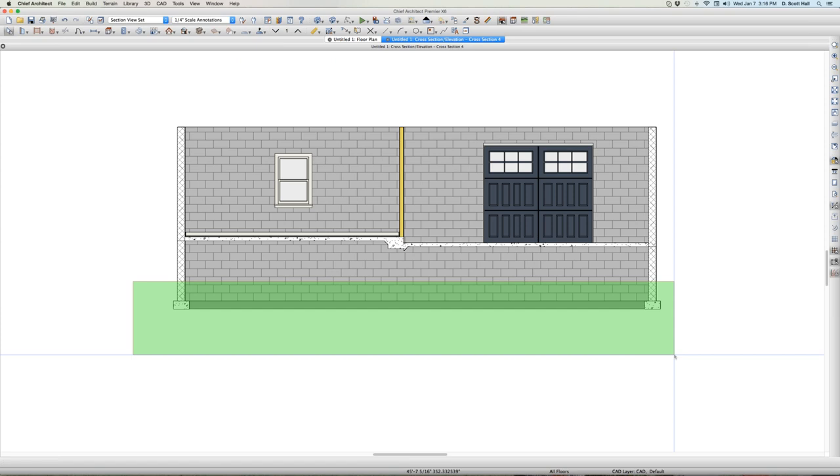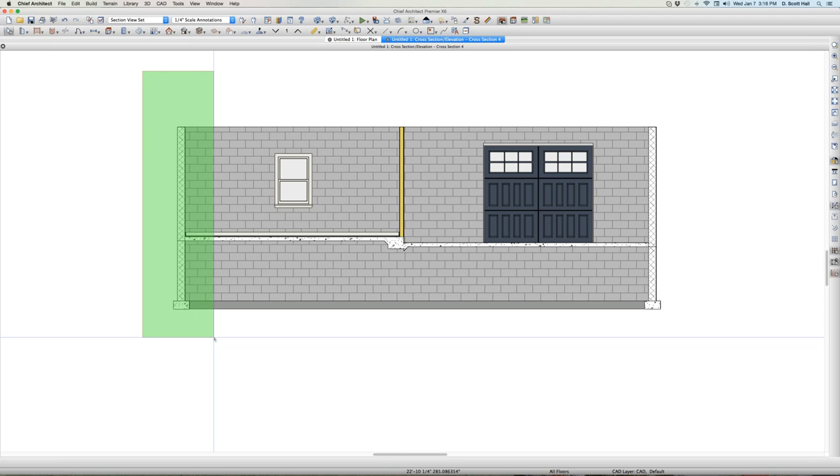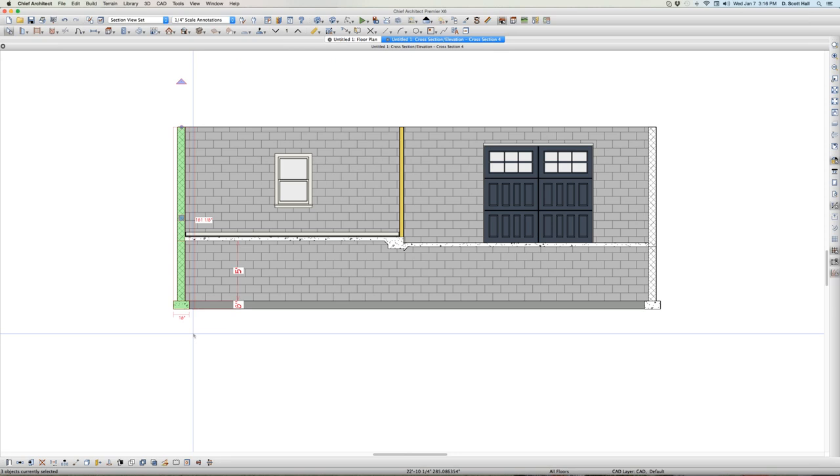Now, the guys up in the Northeast that do basements and what have you, I don't know what they do. Maybe their slab every time sits right at the base of this concrete block wall, this retaining wall. But I am telling you, I'm working on a project right now where that is not necessarily the case, where I do want to have the flexibility of the distance between the top of that footing and the bottom of the slab. I can control it. That's what this is all about.